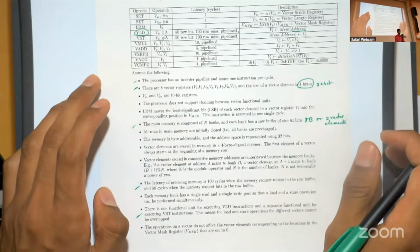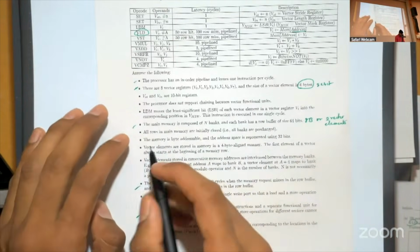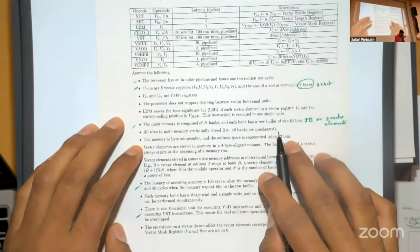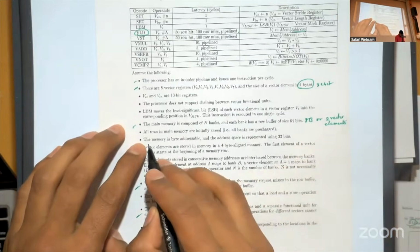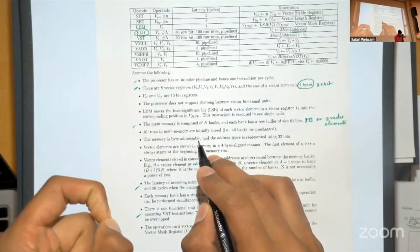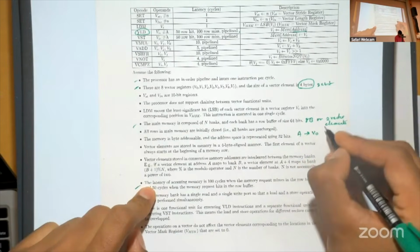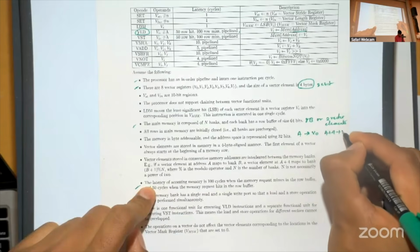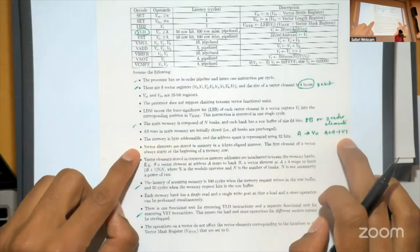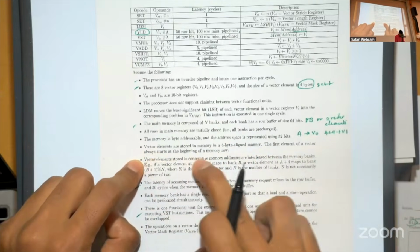Does everyone follow until here? Good. All rows in the main memory are initially closed. So you have to pay the row access penalty, basically, the opening of the row penalty. The memory is byte addressable, which means that you can access 1 byte at a time. Essentially, address A would correspond to vector element 0. Address A+4 would correspond to vector element 1, because it's byte addressable and every element is 4 bytes. They're stored in a 4-byte aligned manner. The first element always starts at the beginning of the row.